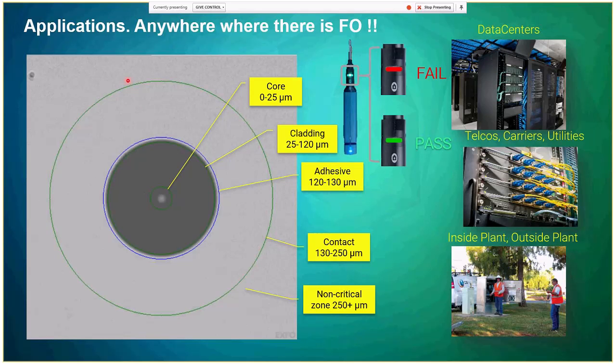And even though today there is a requirement for 4 areas, some operators we have seen as well the need for an extra area where they want to make sure that if they're spending money on the network, they want to have it clean eventually as well on the external area, where if you have particles, they will move inside of the core of the fiber. So this area will keep growing. Meanwhile, we will try to improve our networks. Our equipment will give you the pass or fail thresholds on the unit, even if you don't have the laptop or the mobile phone.